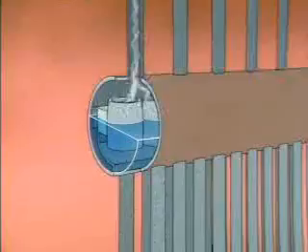The steam produced by a boiler generally contains some moisture. Some plant processes require relatively dry steam, so the moisture could be a problem. To prevent equipment damage from moisture, some boilers are equipped with moisture separators, devices that remove moisture from steam before it's sent to the plant.